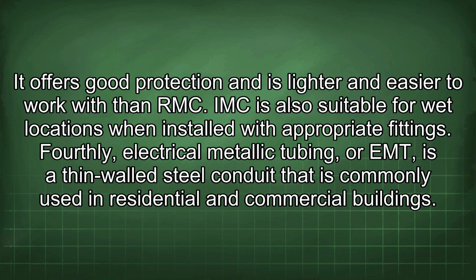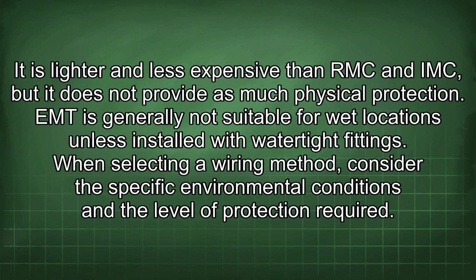Fourthly, electrical metallic tubing, or EMT, is a thin-walled steel conduit that is commonly used in residential and commercial buildings. It is lighter and less expensive than RMC and IMC, but it does not provide as much physical protection. EMT is generally not suitable for wet locations unless installed with watertight fittings.